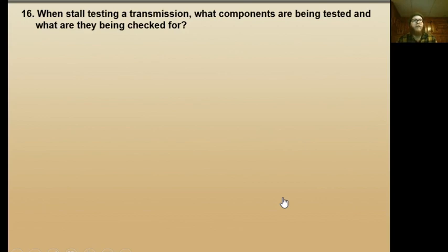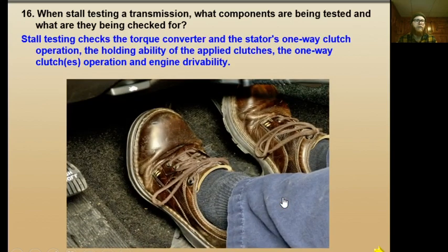When stall testing a transmission, what components are being tested and what are they being checked for? Well, we're testing our brakes even though it doesn't say that, right? Because if the brakes don't work, stall testing is not really going to do us much good. So make sure that your brakes hydraulic system is working properly.